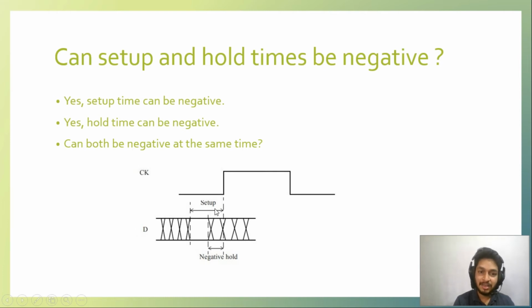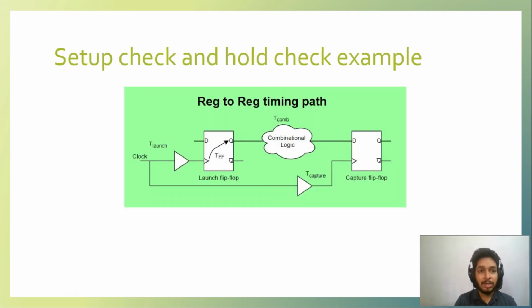So this setup time increases as hold time decreases. So this is a requirement, and this setup plus hold time can never ever be negative. Okay, so this is a positive requirement. So if we make some arrangements to make the hold time negative, we may end up with a positive setup time. So that becomes a problem. Again, the vice versa is also true.